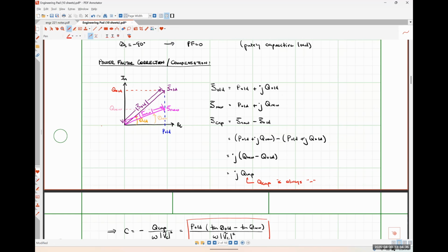Or it can be a thyristor valve controlled system as well. For the inductors, it's always a thyristor valve controlled system. So effectively, you just have one big honking inductor, able to correct any type of leading power factor that you might have, and you use the thyristor valve and a particular, what's called a firing angle. And that firing angle is essentially related to a duty cycle that is saying like, I'm only going to have the full inductance connected for a specific portion of a half cycle, okay?